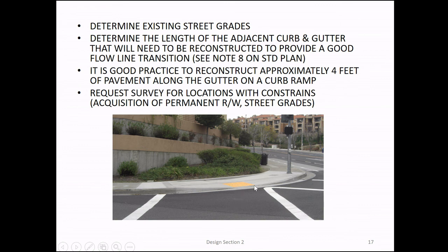And you cannot move the location of this curb ramp too far to the BCR, because from this point here to here, you have to have a minimum of 4 feet. So from the ramp edge to this point should be 4 feet minimum. That point being the white stripe. Correct.